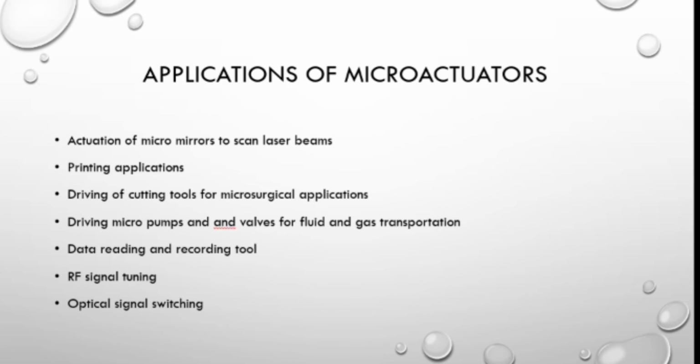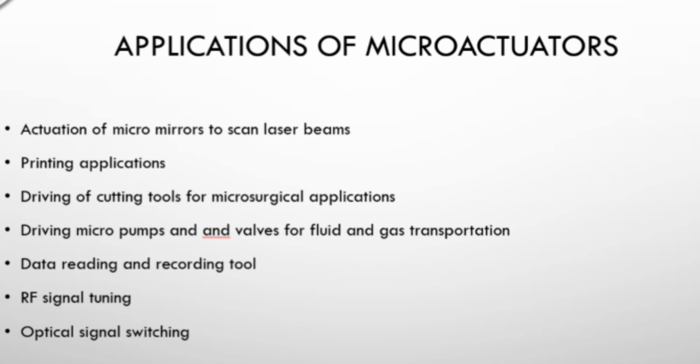Applications of microactuators include printing, actuation of micro mirrors to scan laser beams, driving of cutting tools for microsurgical applications, optical signal switching, etc.